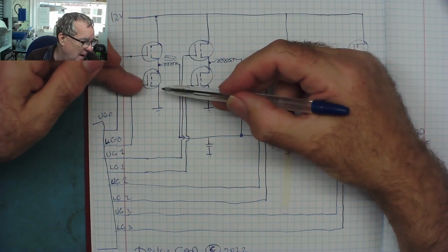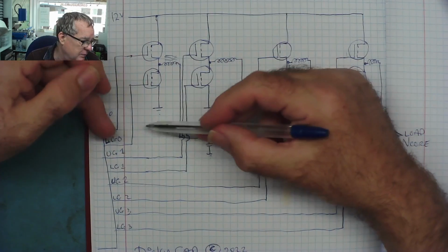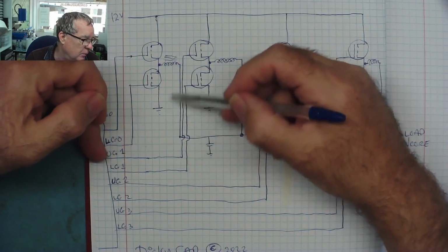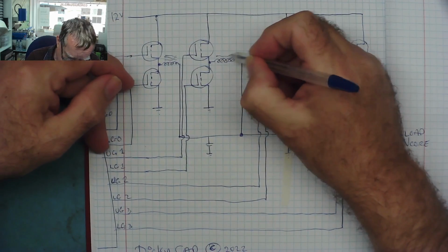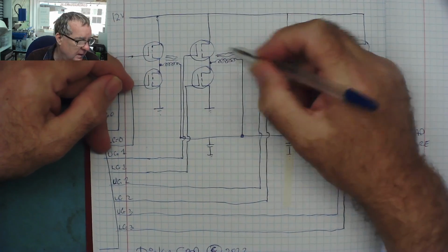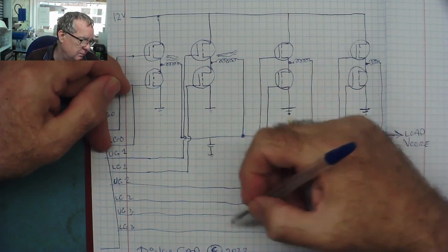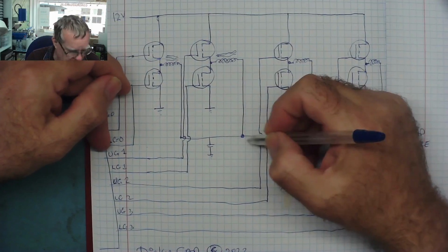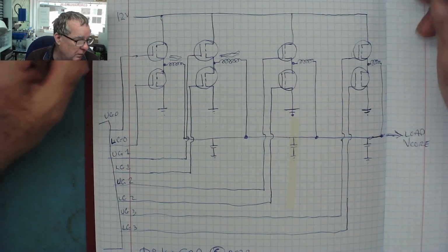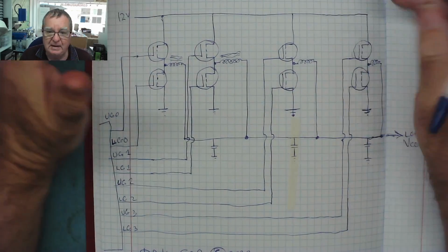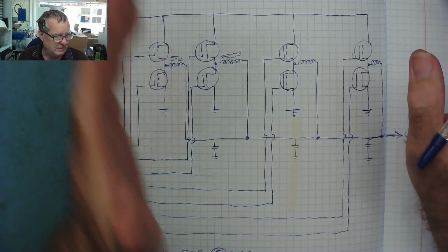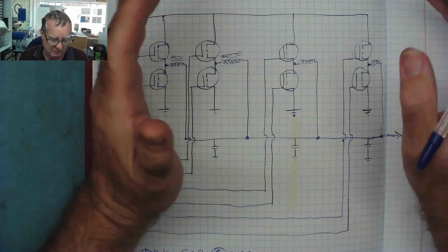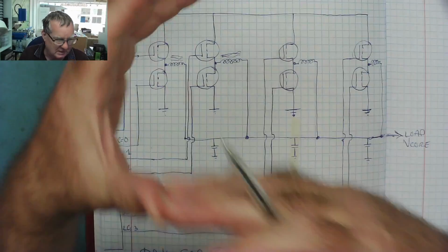Once that's happened, while this is still collapsing, it then switches on upper gate 1, powers this one on, and this charges this coil up with magnetism. And the same thing, switches off, switches on, and again that discharges into there. And that happens for all 4 phases. You can think of this a bit like a 4-cylinder car, where each cylinder has got a different phase.